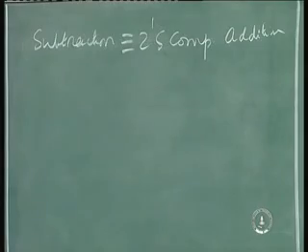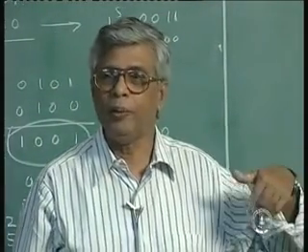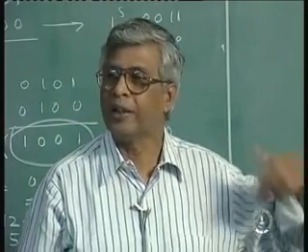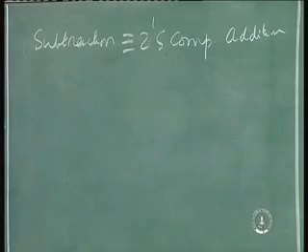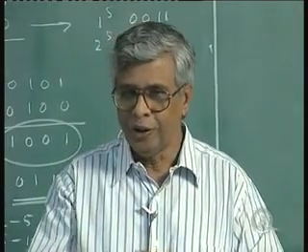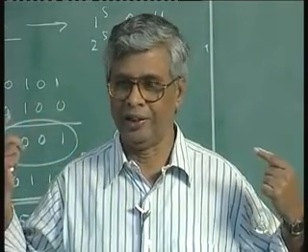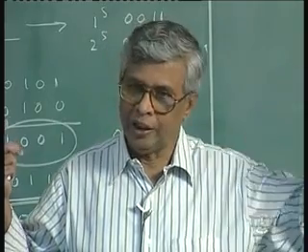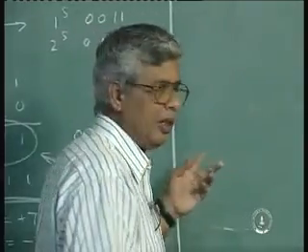Okay. Now, next step is how am I going to convert a given number to 2's complement before I can add it. So first let us do 1's complement. That is why I told you hardware-wise it is easier to do 1's complement and plus 1, even though in principle you could do this borrowing from the previous, all those things I want to avoid. A simple complementing will give you 1's complement. All I have to do is to add an extra 1 somewhere. I can do it at the beginning or I can do it at the end. Is it not? So 1's complement is an inverter.